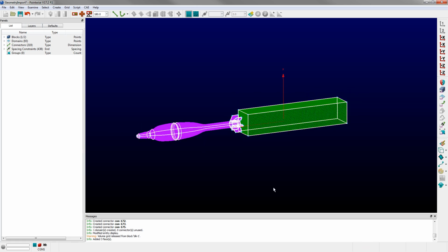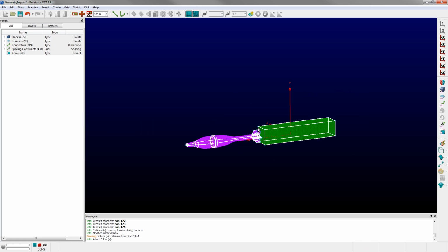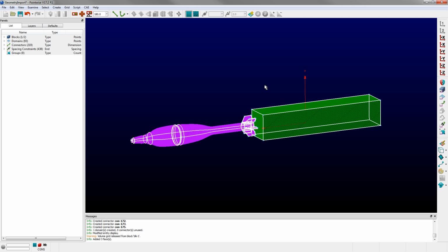So now if I select, you'll notice that's an interior face in my block. And all I have to do at this point is just go up to the toolbar and click Initialize, and it'll reinitialize that block with the new information. All the TRex stuff is stored. You just click that block, it'll regenerate the TRex region, it'll recreate the isotropic TED region, and then you're done.